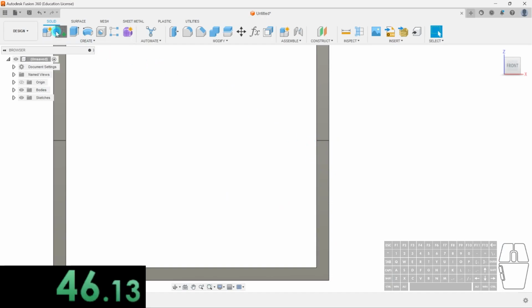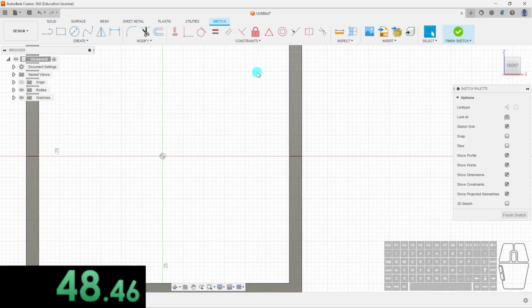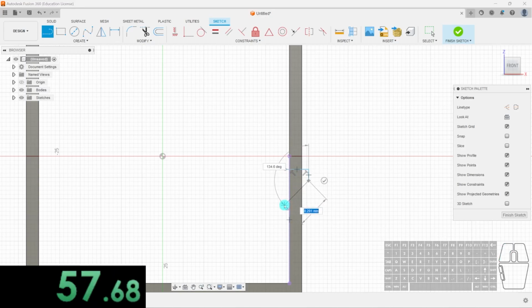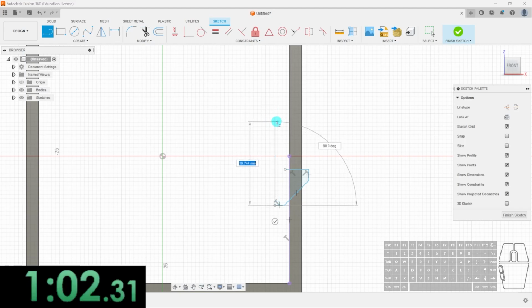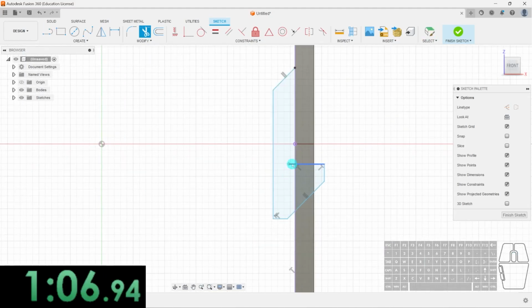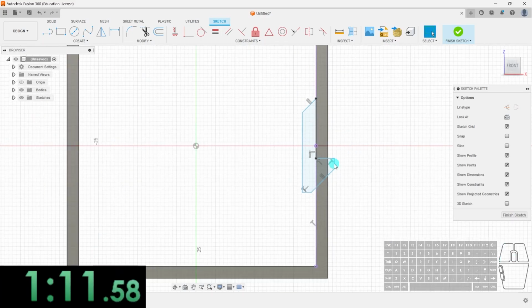So what I want is to create a sketch on the side plane so that I can draw my joint. In this case, I'm just going to draw a line through here, through there, at an angle. Again, the more exact dimensions will be in the document, and like so. Okay, and I'm going to just use this to trim. Draw another line to connect everything together. And now I have my face like so. I can always press here to delete my projection, and you can see I've got my whole face.